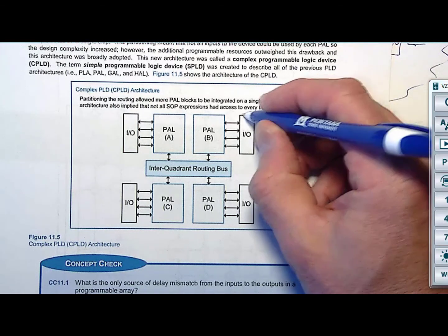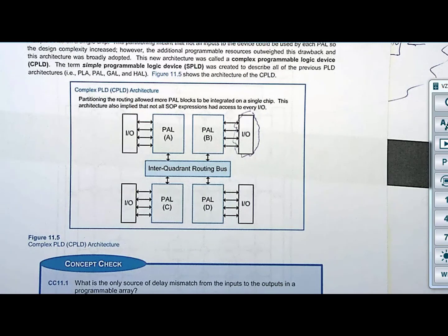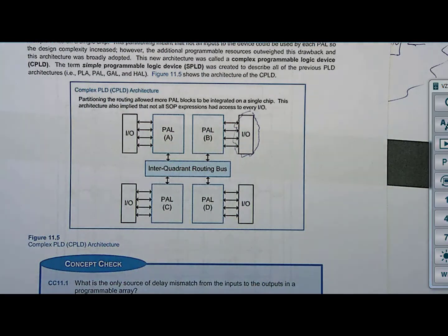The I/O was the macro cell. They still had these macro cells in there, which were super important because you were trying to build complex digital systems. But this is the CPLD. Now you will hear people say CPLD, and what it represents is just a programmable logic device. There's really no other way to describe it other than PLD. But the history of it is bringing all this stuff together and getting to the point where you had an architecture built on basically arrays of PALs.